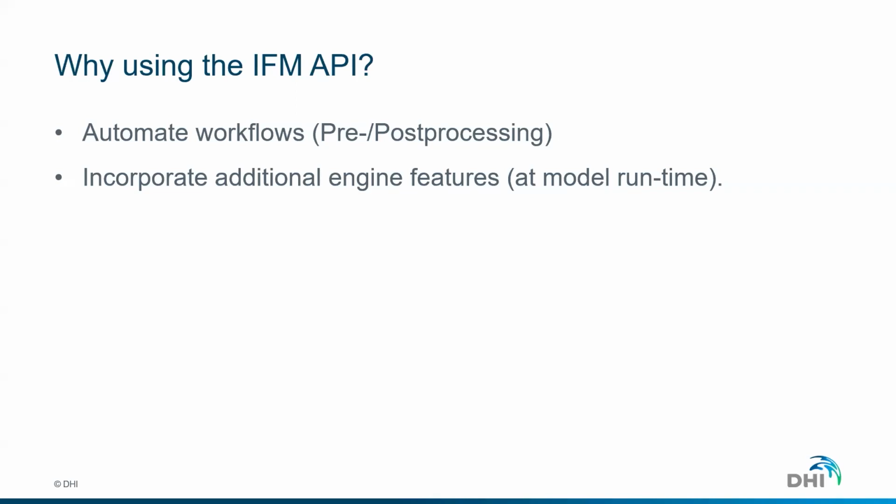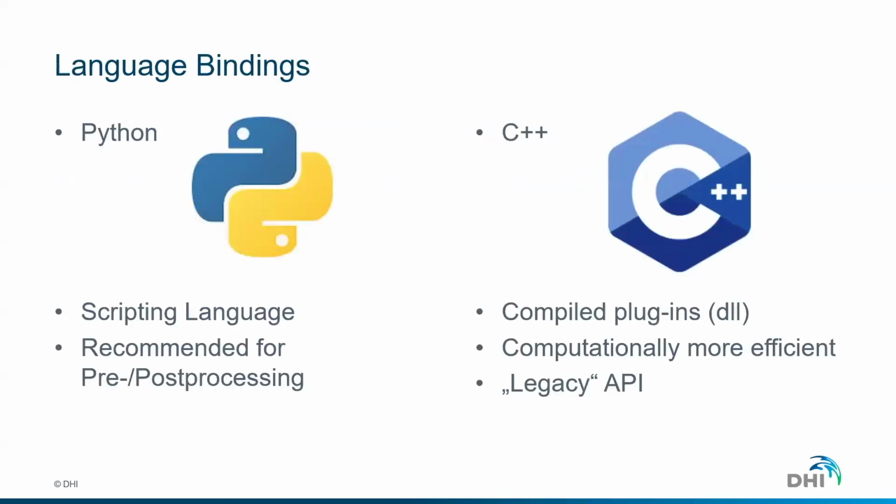So now, with one single Python script, you have the whole workflow from model conceptualization, mesh generation in 2D and 3D, parametrization, and post-processing. And of course, you can also use this programming interface to extend the capabilities of the software. Some users have developed plugins or scripts to incorporate different physical processes on top of what FEFLOW can offer today.